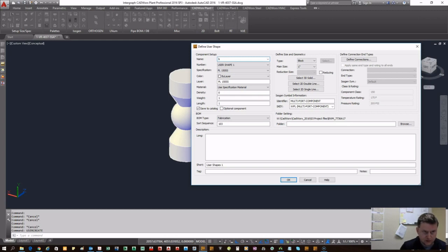It's good to come up with a standard notation that you use for this. We're going to make a socket weld ball valve, and let's say we have a particular vendor like Fisher. You can build multiple sizes into a data table, but the problem with that is you need to make sure that their qualities match up, because you're only going to specify one length right here. As long as the length isn't an issue where you don't want the metadata to match up properly, then you can put multiple sizes in there without causing too much of a hassle.